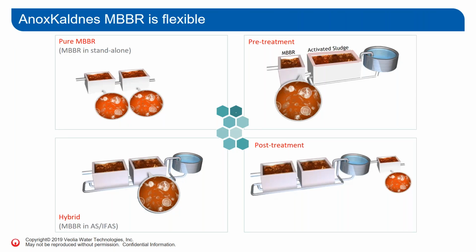It's very flexible. So I will say that MBBR is a technology, it's not a process. And then you put this technology into work and you make a process out of it, which could be like in the first case you see here, we say pure MBBR. So you have only MBBR reactors, which could be one reactor in some applications, or two, or it could be many, depending on the complexity of the treatment, what you need to achieve and what the wastewater is like.